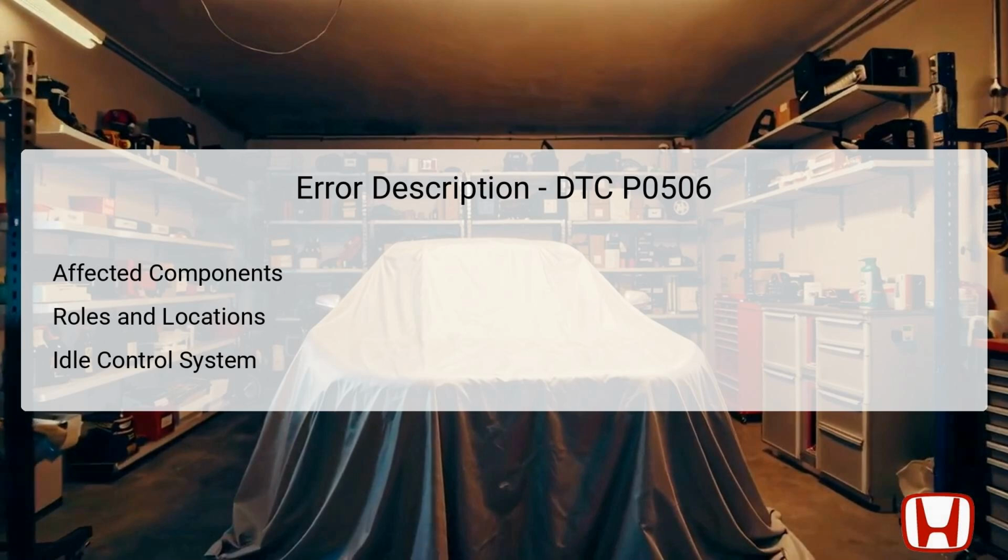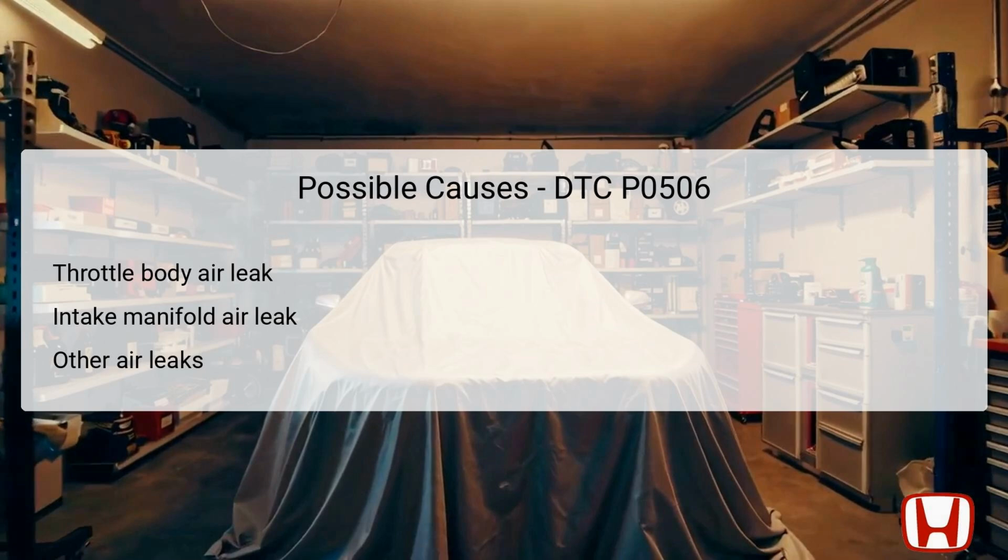The PCM uses these inputs to determine the target idle speed based on various conditions such as engine temperature and accessory load like air conditioning. If the actual idle speed is lower than the target by more than 100 RPM for 20 seconds, the PCM identifies this discrepancy and stores the DTC. It's crucial to understand the locations of these components. For example, the throttle body is typically mounted on the intake manifold, making it easily accessible but integral to vehicle operation. There are several potential causes that may lead to the P0506 code.